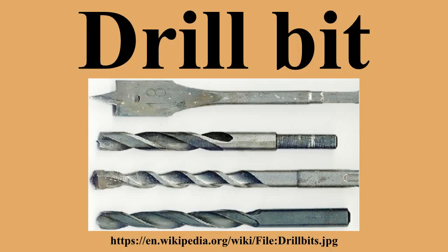The bit is hardened and coated against wear far more than the average drill bit, as the shank is non-consumable. Almost all indexable drill bits have multiple coolant channels for prolonged tool life under heavy usage. They are also readily available in odd configurations, such as straight flute, fast spiral, multi-flute, and a variety of cutting face geometries. Typically, indexable drill bits are used in holes that are no deeper than about 5 times the bit diameter. They are capable of quite high axial loads and cut very fast.